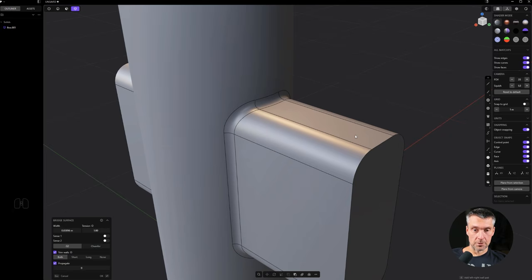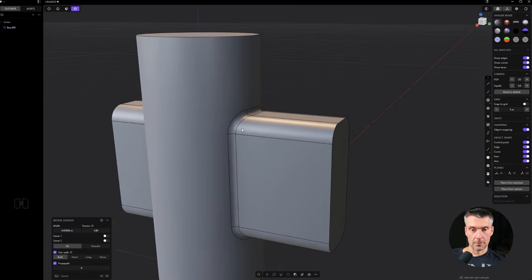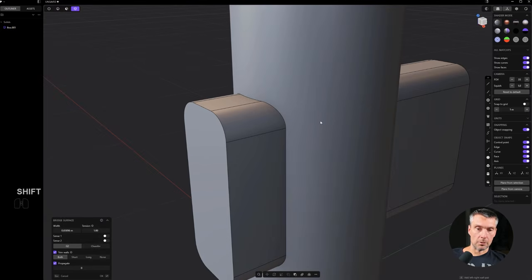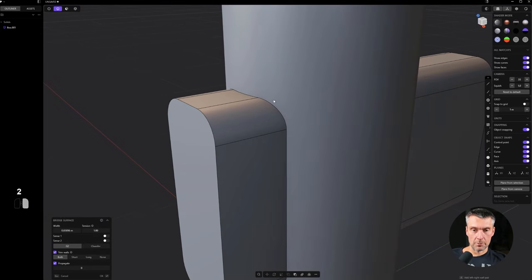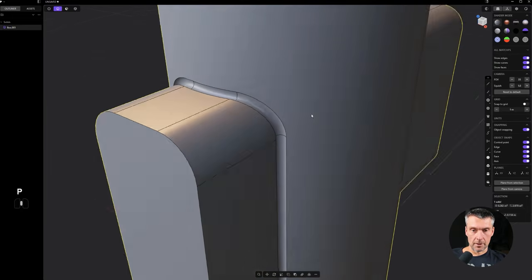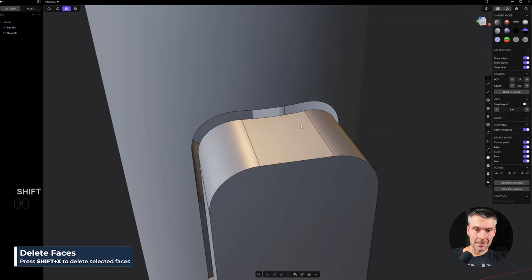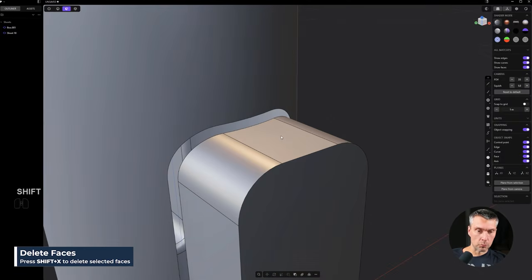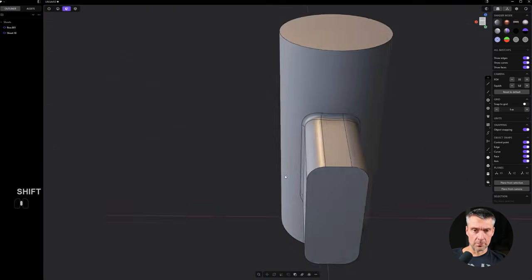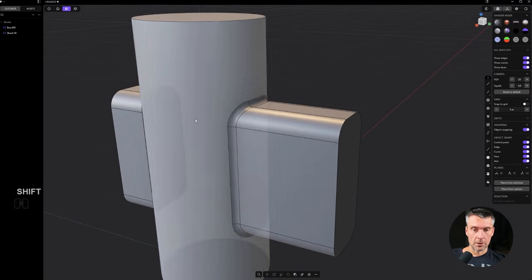I mean, this is magic. You know what I mean? This is so cool. I'm absolutely loving this. This is one of the coolest features, and it's going to save you so much time. Before, we had to run a pipe. So let me show you, right? We had to press P for pipe, then cut this, then remove this entire thing here, and then we had to bridge it through lofting. It was really annoying, right? You had to draw isoparam edges. It was a nightmare. This is absolutely brilliant. One of the best features introduced recently to Plasticity.